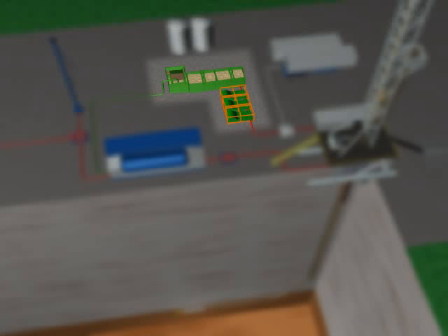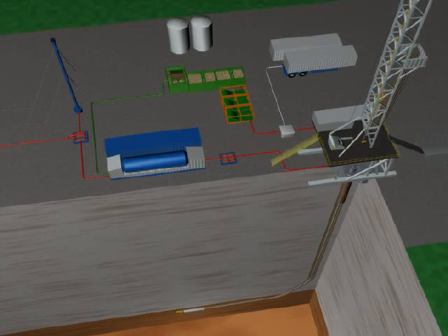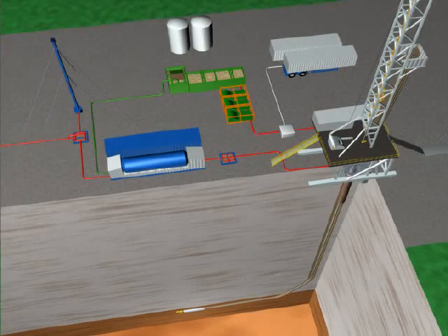The separated hydrocarbons are sent on to production facilities or flared. The light fluid is pumped back to the rig's mud system for treatment and reuse. This completes the tour of the main surface systems that are used in 2-phase underbalanced drilling operations.